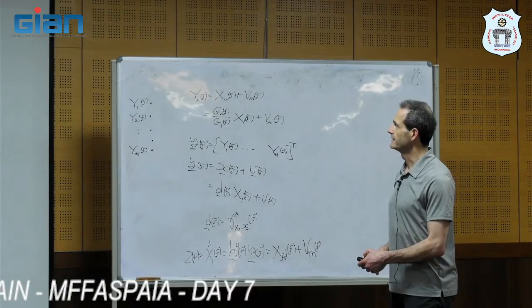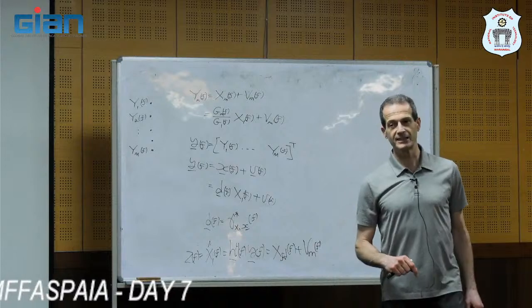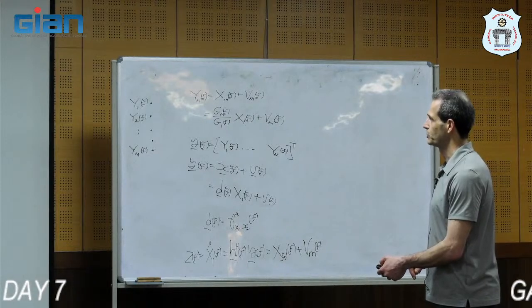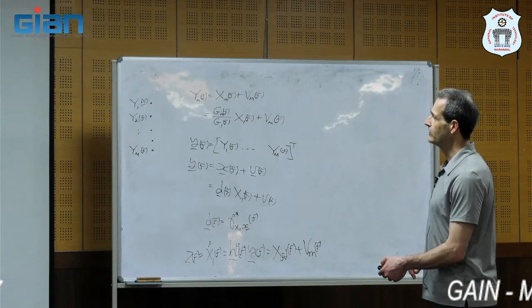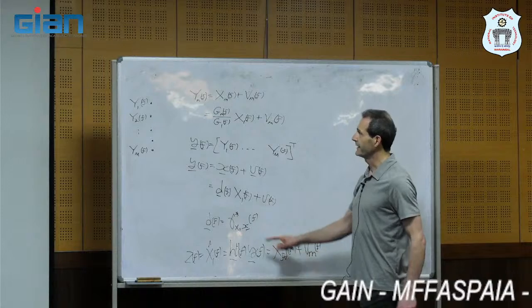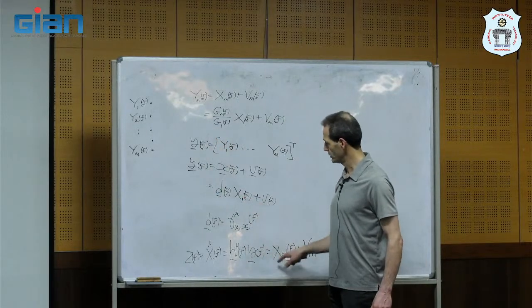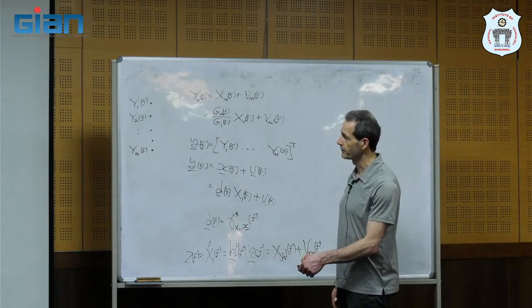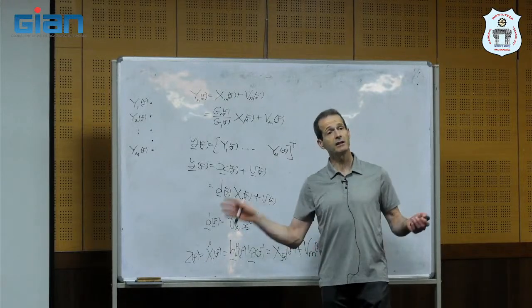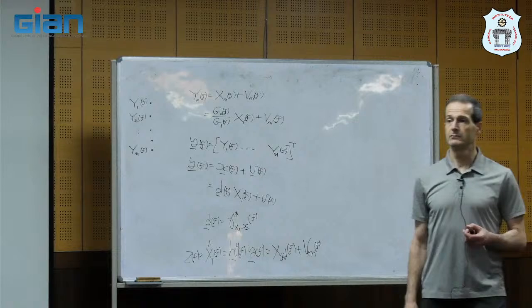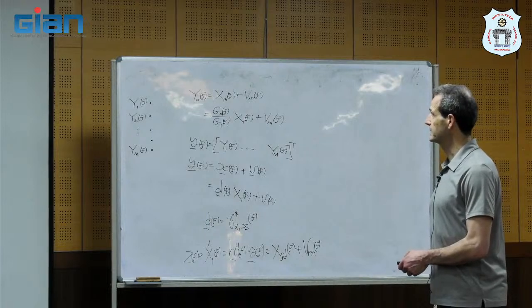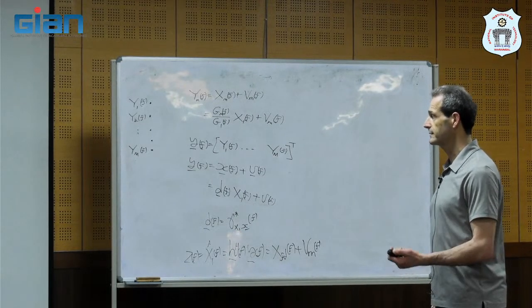Okay, so the desired signal reduction factor, and then we also have the desired signal distortion index, narrowband and broadband, which means what is the mean squared error between X filter desired and X1. What is the mean squared error between them, normalized by the variance of X1. So this is the distortion. As we know, it's similar to what we defined for the single channel in the frequency domain.